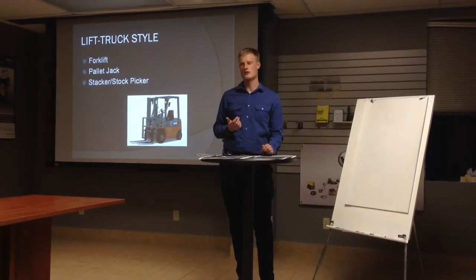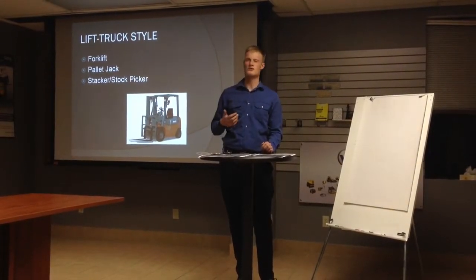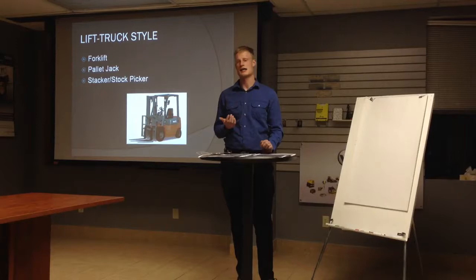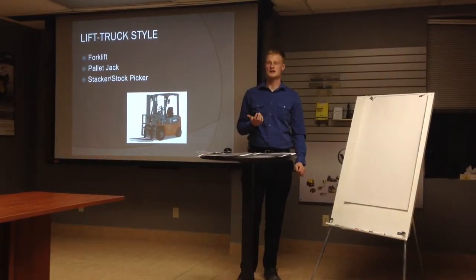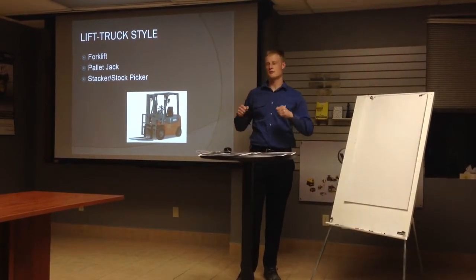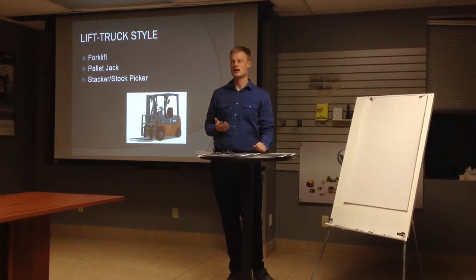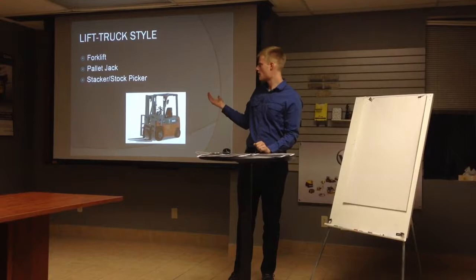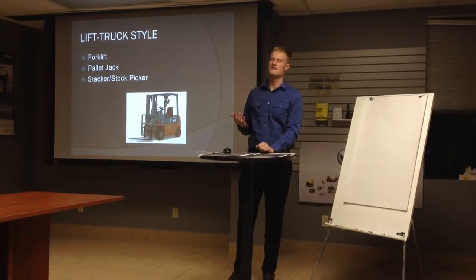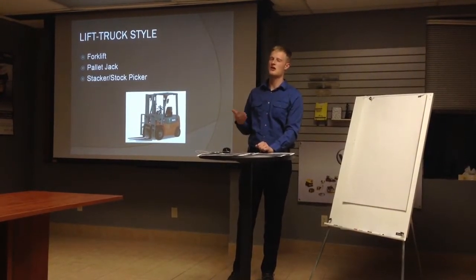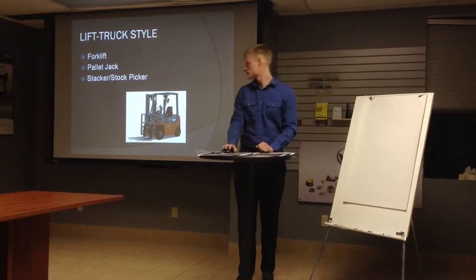Also, the ease at which a lift truck moves in and out of the back of a trailer. Again, if it's a hand pump jack, it might be a lot easier for the person to maneuver, and it may call for an edge of dock leveler, whereas a pallet or a forklift may call for a more heavy duty scenario, such as a scissor style or pit style leveler.